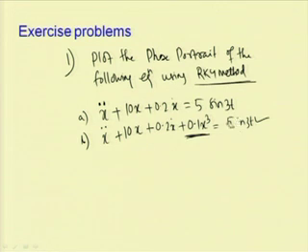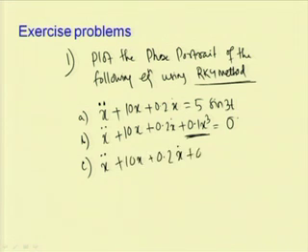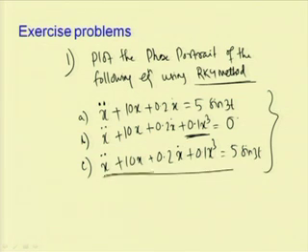First take the forcing term equal to 0, and in the third take a forcing term: 10 x plus 0.2 x dot plus 0.1 x cube equal to 5 sin 3t. Solve these three problems using the RK4 method, then solve the second problem using the straightforward expansion method.